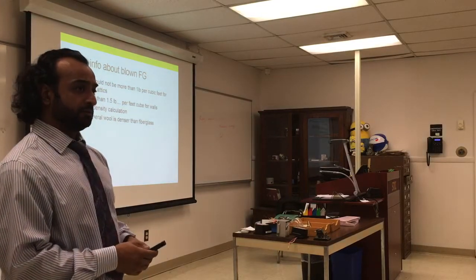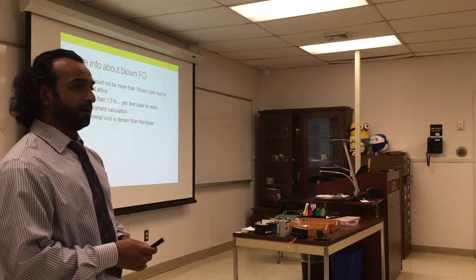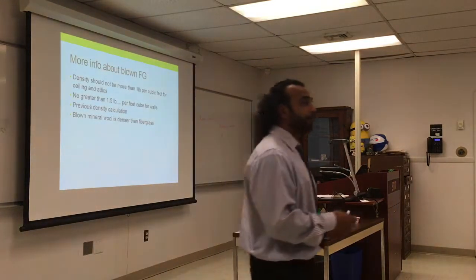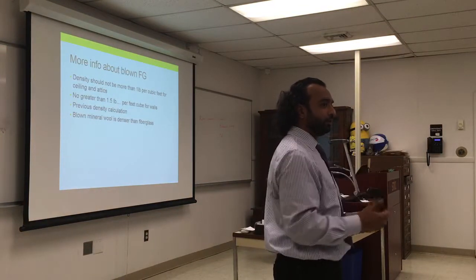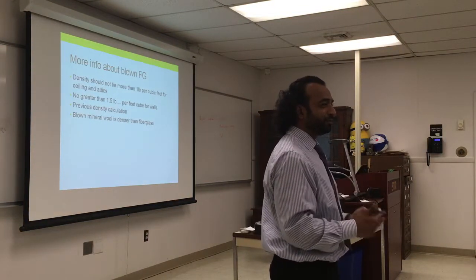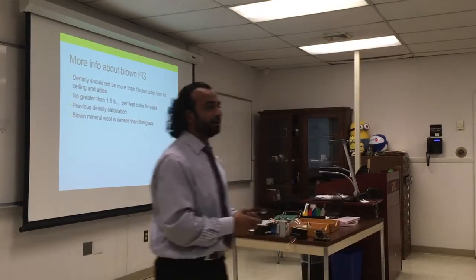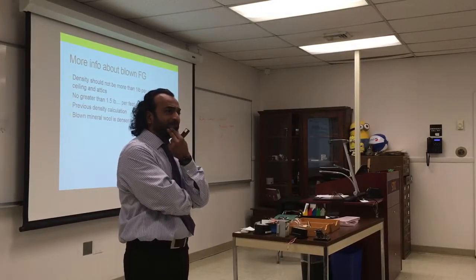It's a lot of insulation on that house. Usually you want to insulate more to the outside wall. Insulating between rooms is not that useful, unless it's a different unit or a different floor. But these were all outside walls.